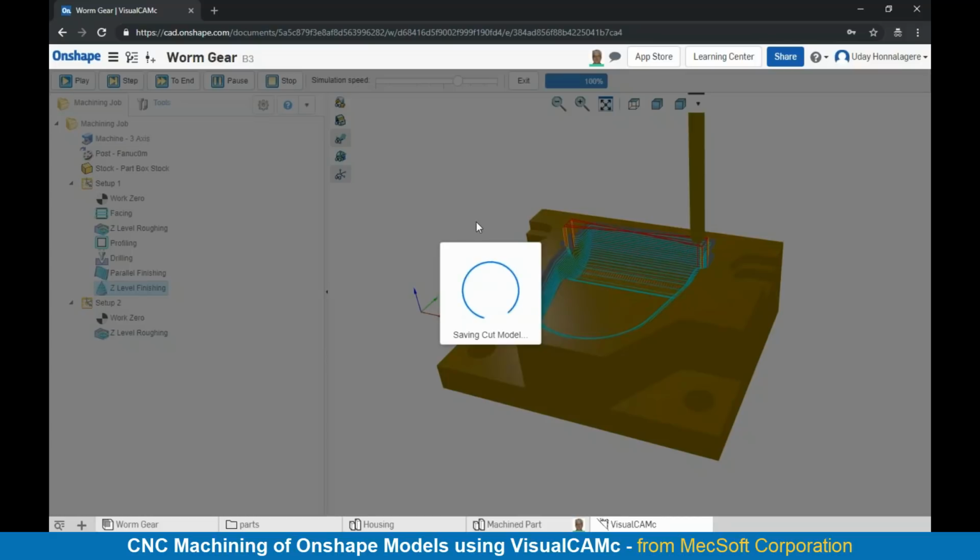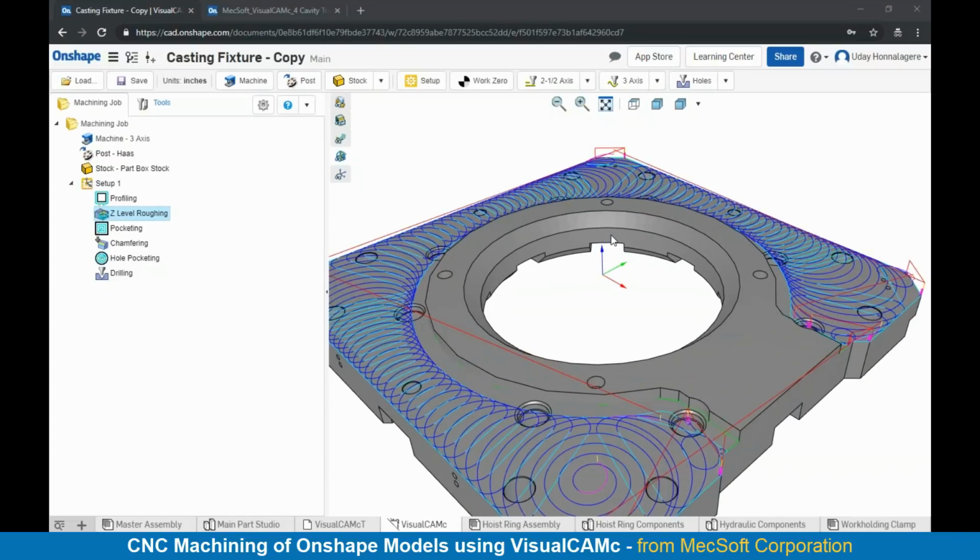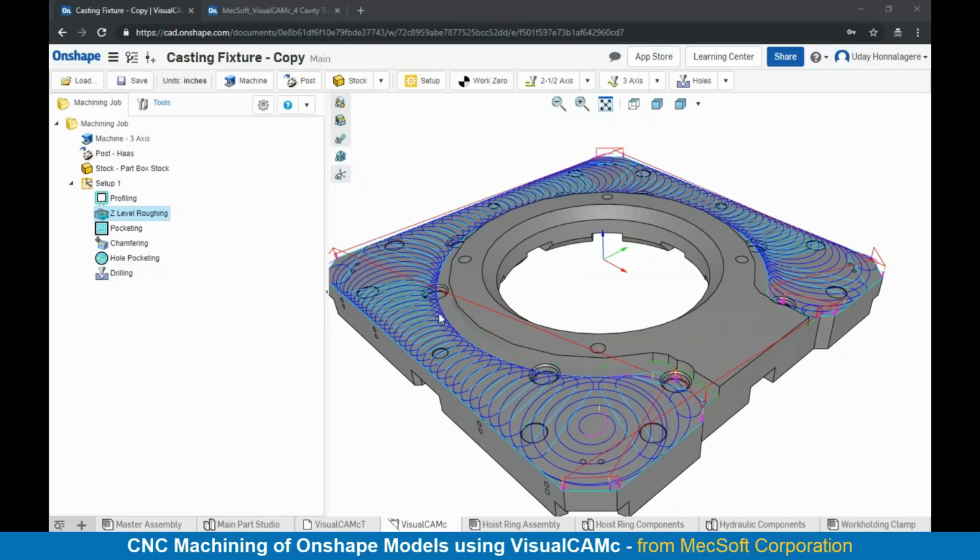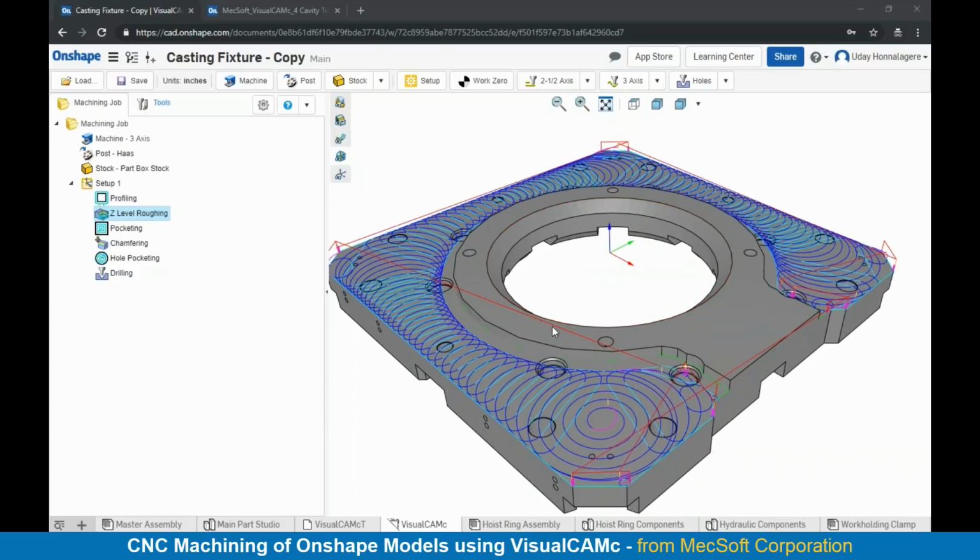Now, while we are waiting on that, I do want to quickly show you some of the types of toolpaths that you can generate on different classes of parts or complexity of models. So for example, here you're looking at a high-speed cut pattern toolpath that can be employed in a roughing operation, where you can generate very efficient toolpaths for roughing. It's generated by use of a constant tangential arc, which you can run at higher feed rates, and it basically prolongs your tool life and reduces wear.